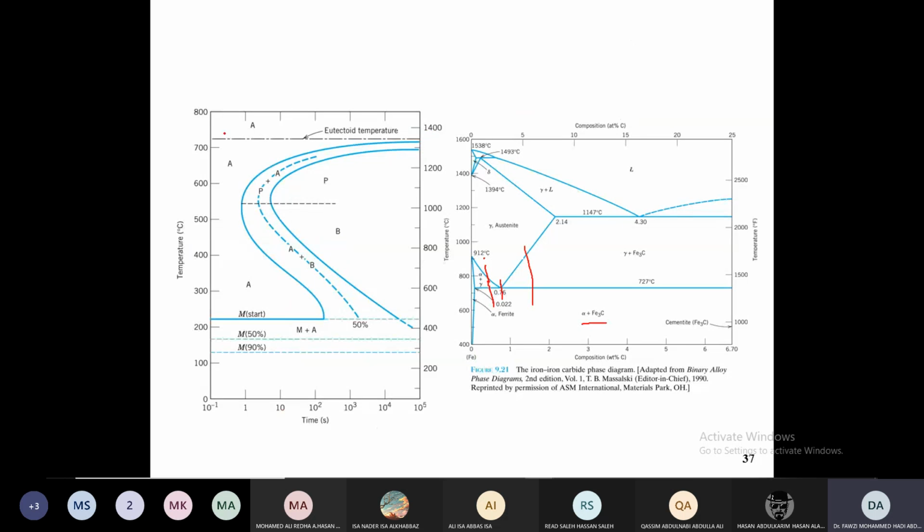and when we say moderately cool, we don't stick to the condition of using the phase diagram. This means that our cooling rate is so high that the phase diagram cannot predict for us what microstructure will develop, and that is in the slow cooling. But in moderate cooling, you avoid the nose of the TTT diagram, and you will be producing the bainite phase basically.